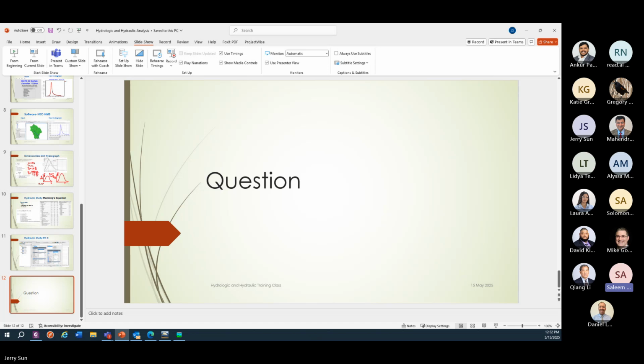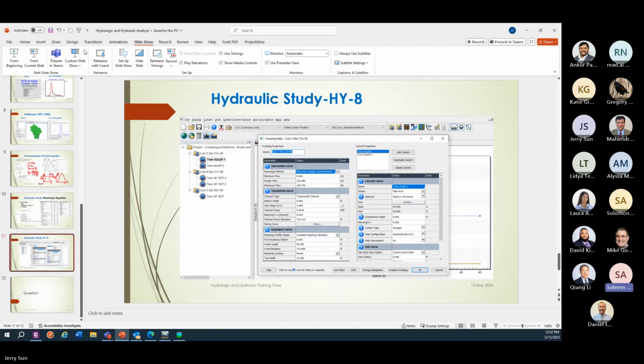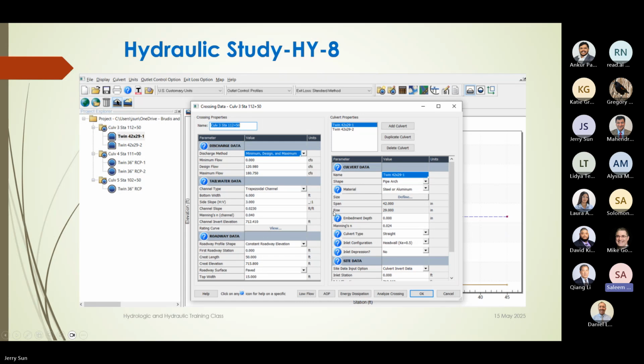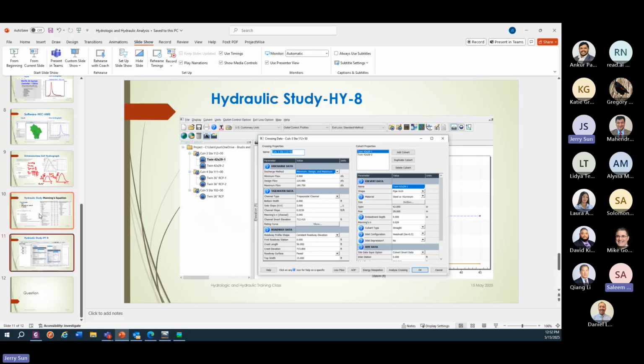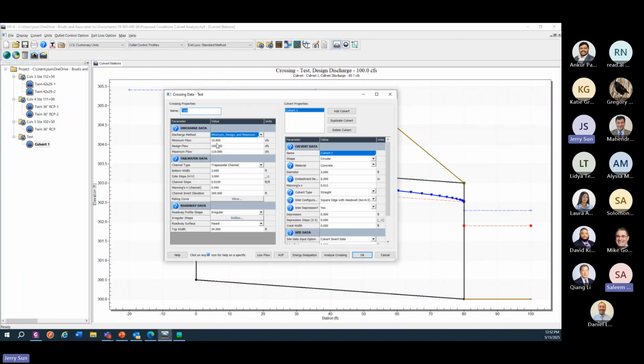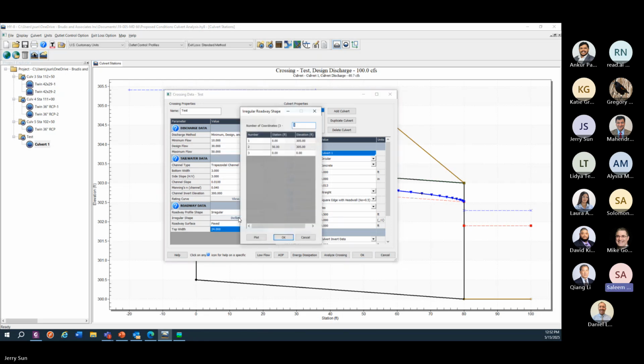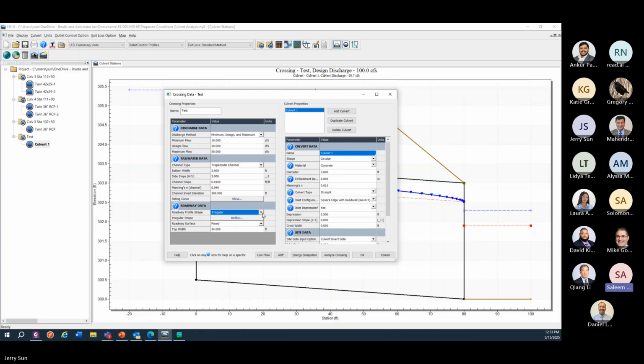Go to your culvert analysis. Okay, so now we have 120. Go back to your original discharges, which you have used. What were those? So 15, 10, 30, and 50. Okay, and what is this? Maximum flow is 50. Yeah, and then let's change the diameter to 2 feet.